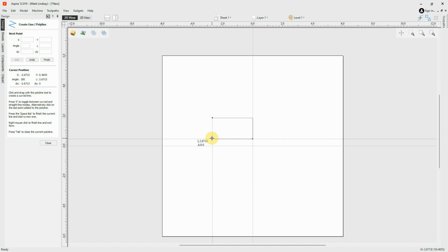And you can see those guides. I'm right in line with that point, that first point I entered. Then I can click and then pull my cursor straight up. And then to close this vector, I just tap the tab key. And it closes that vector. So I don't even actually need to find that point. Just hit tab and it finds it and closes it automatically.